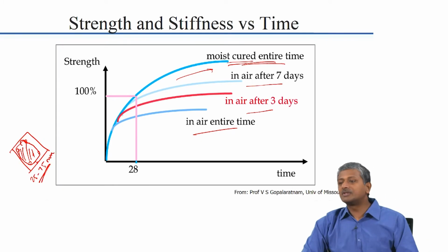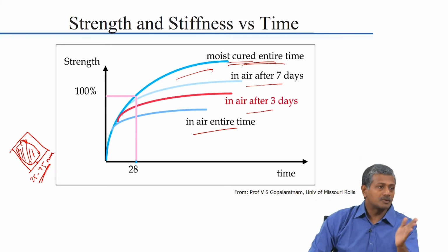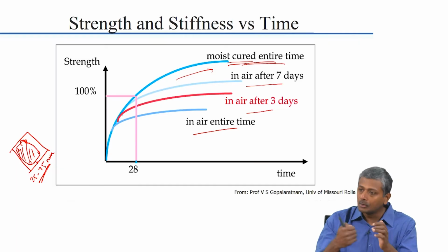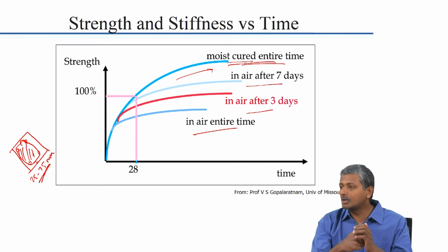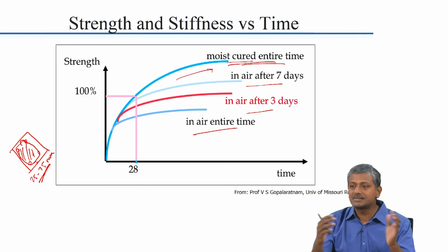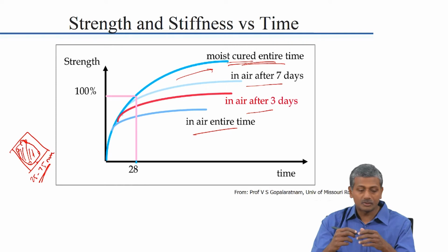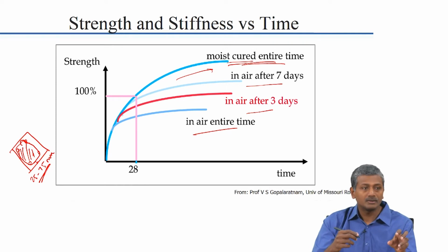You can't imagine that with the fine pore structure that concrete has, the drying atmosphere prevalent on the outside can start drying out water from 30 to 40 millimeters into the concrete. That may not happen. So, the concrete that is sitting inside the reinforcement is something that is continuing to gain strength because of its continuous hydration process, right. It is only the cover concrete which is responsible for that poor pore structure that develops when there is no curing.